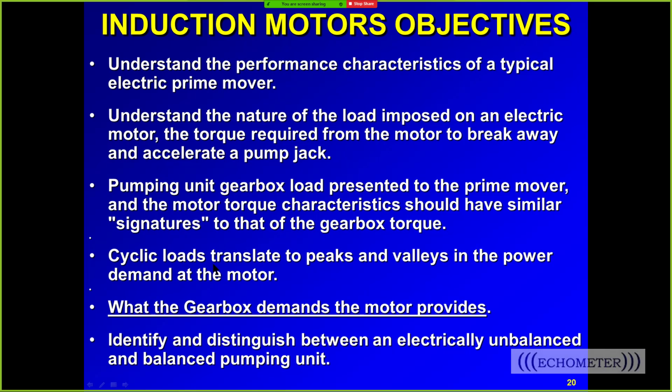The cyclic load is how the torque varies throughout the stroke. And the cyclic load change, once you balance it, represents the change in energy use. So when you compare the cyclic load unbalanced to balanced, the change in the cyclic load is approximately equal to the ratio that is a percent change in your power use.